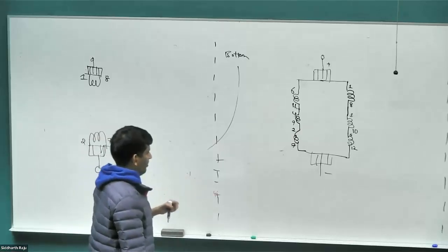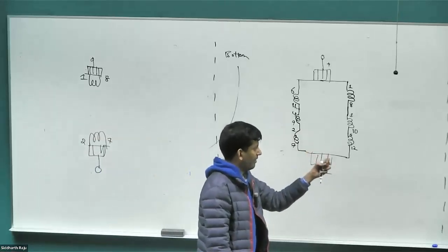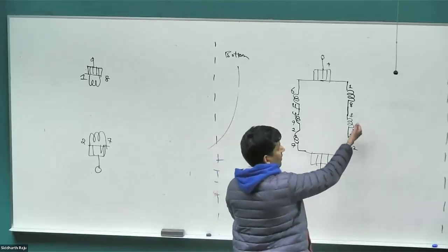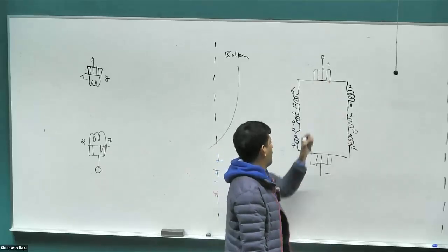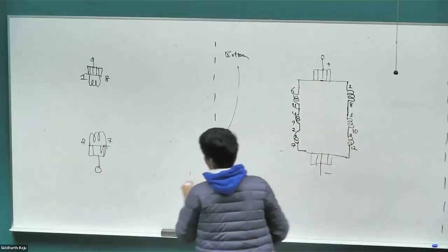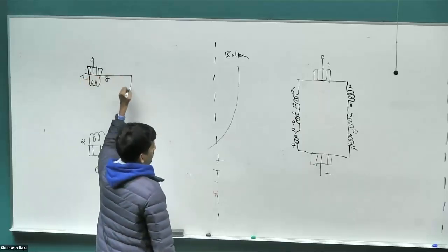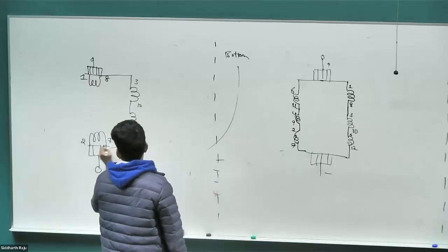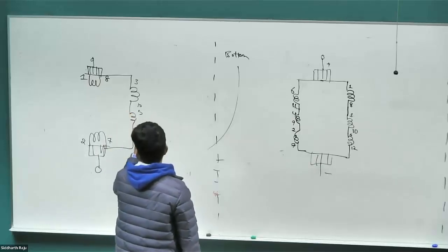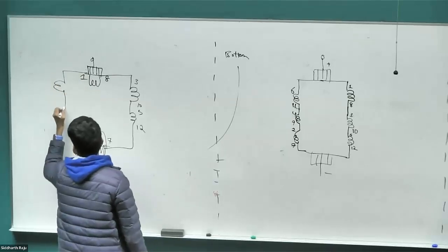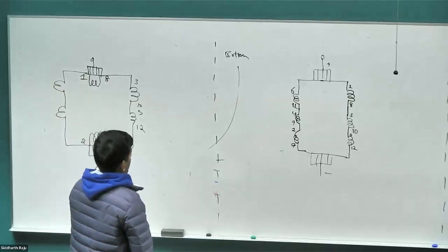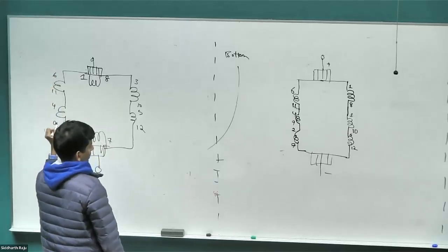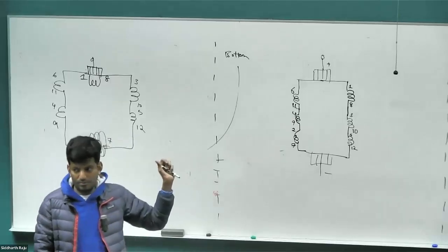And then the rest of the conductors are pretty straightforward to draw. We can go through the same process again, trace that. But if you can see what's going on here, it's basically these sets of coils are rotating, right? As they rotate, these two got shorted, and these two got shorted. The rest of the coil set just moved around. So we have 3 and 10 now here, and then we have 5 and 12 here. We have 6 and 11, and then 4 and 9. Yep. Right? Everybody clear on this part?